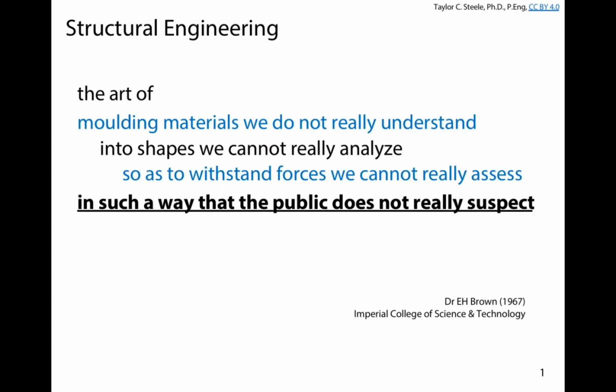And then in lectures 5 and 6, we talked about the types of gravity loads. How do we figure out what the uniform load is that we're actually getting these loads for? We talked about dead, live, and snow loads. Generally, take them as uniformly distributed in the sense that they're going to generate maximum actions that we expect our structure to see during its life.